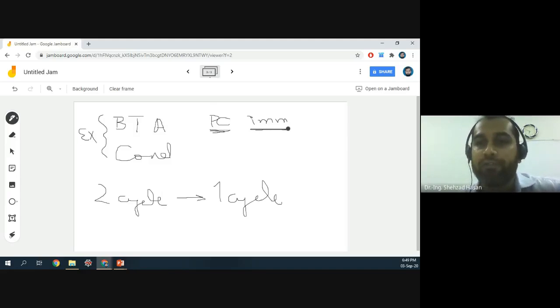So you're going to fetch the instruction, take the last 16 bits of that instruction, and that would be the immediate value. So if you're going to calculate the BTA without elongating any operation, then this immediate value is available only after fetching the instruction. So this means you cannot find the BTA in the fetch stage, but you can do that in the next stage, which is the decode stage.